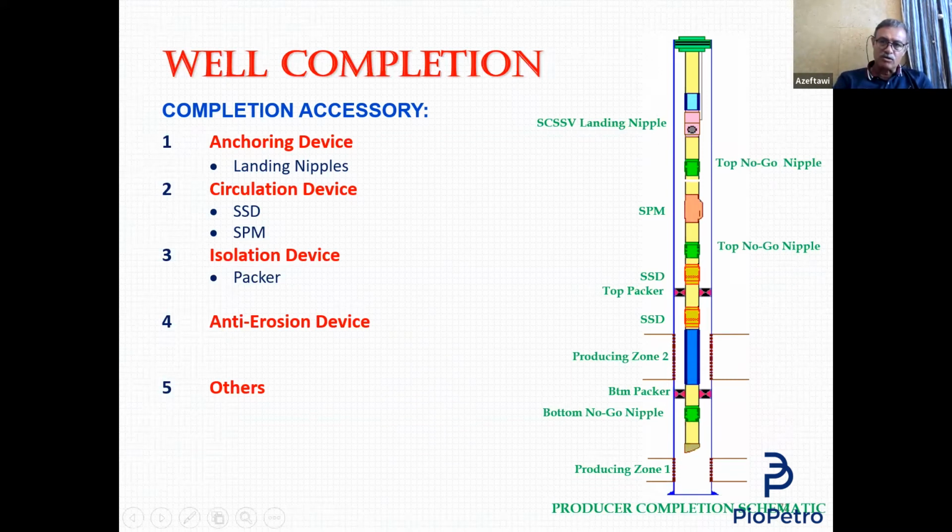This is the tubing hanger that hangs the top completion. What hangs the bottom completion? It is the packer. What's the bottom completion? Actually, the bottom completion is a couple of joints, having some accessories like wireline entry guide, a couple of landing nipples, maybe a perforated joint, maybe permanent gauges.